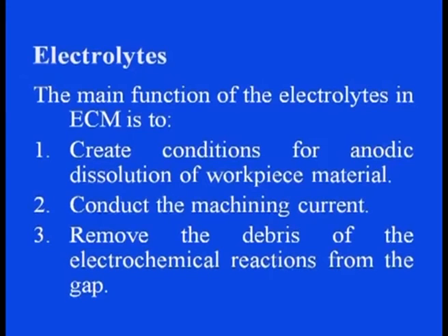Now, let us look at the characteristics or the functions of an electrolyte in ECM. The main functions include: number 1, create conditions for anodic dissolution of the workpiece material. Number 2, conduct the machining current, as we have already discussed. This is responsible for movement of the ions.